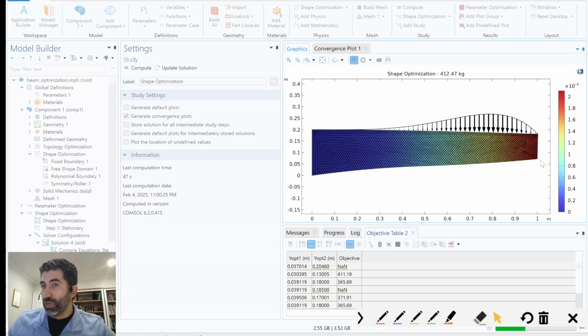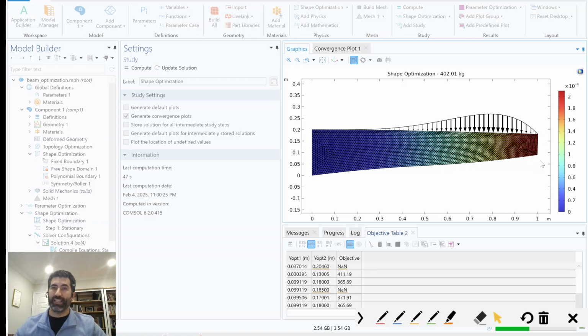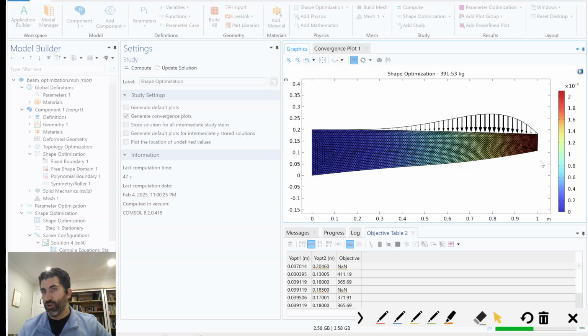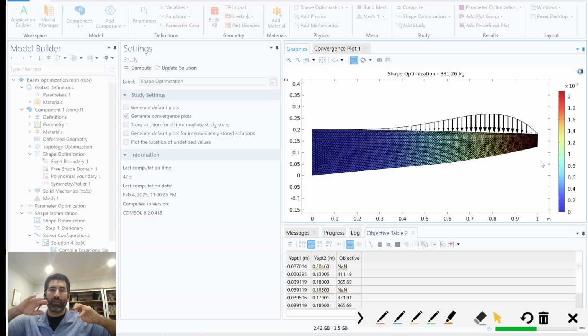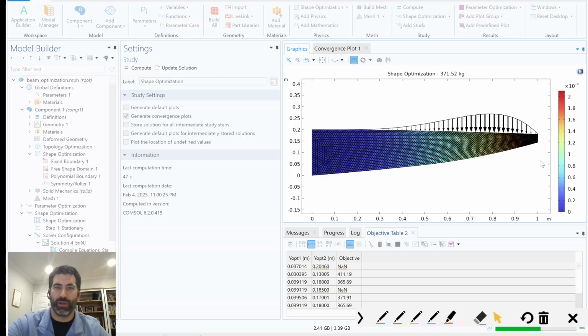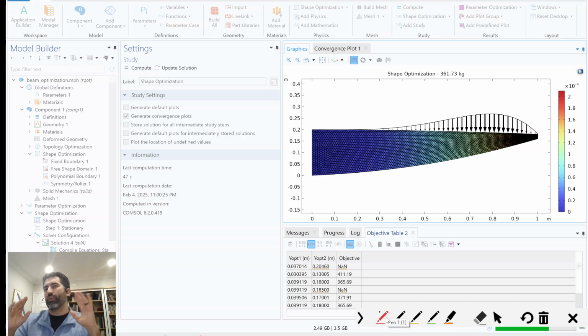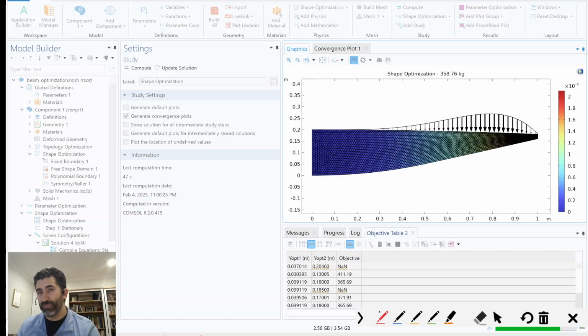Meanwhile, what's actually happening in this case is that we're not redrawing this geometry at each point. Rather, we're moving this boundary, this polynomial boundary at the bottom, and then we're deforming our original mesh to conform to it. So this is another application of frames of reference, which you might remember from the past lecture. And here now, instead of a moving frame of reference, we're just deforming our geometry.